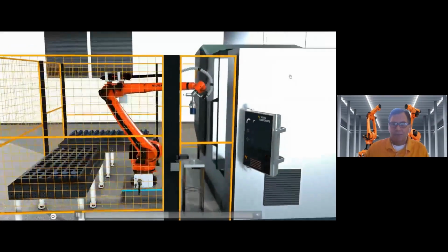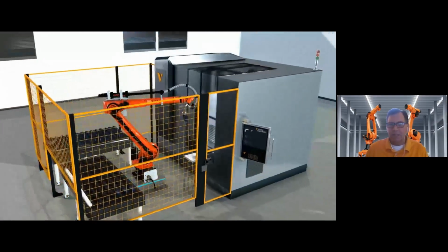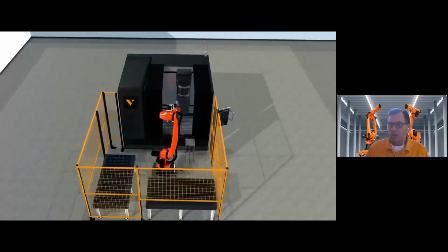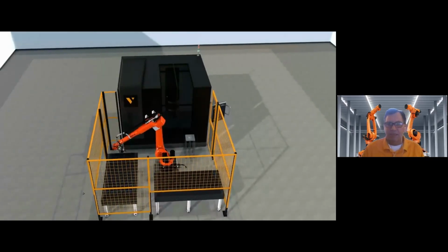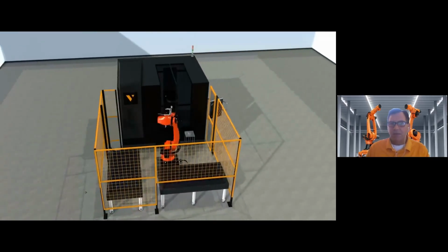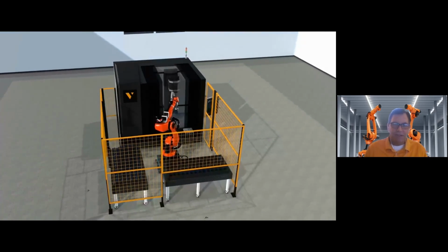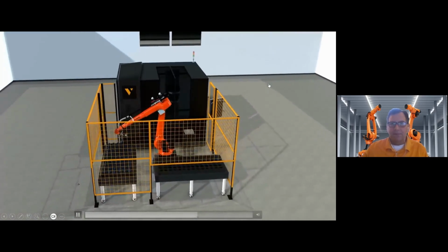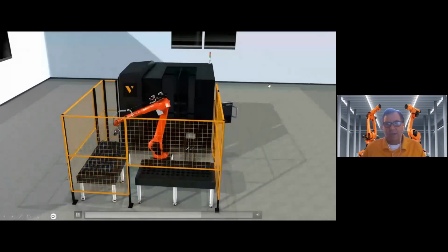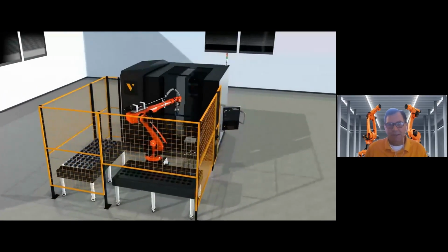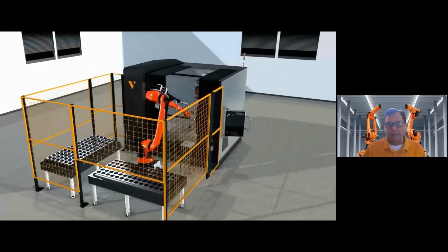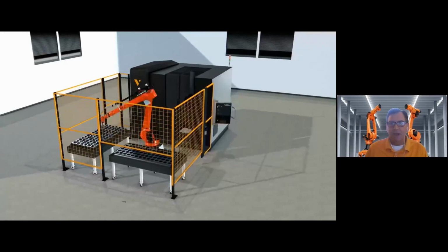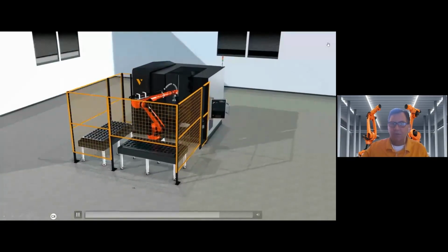Here's the same simulation, but a higher-end, more realistic simulation to show the whole process. So you can look at different views. You can see if there's going to be any potential bottlenecks within your facility, and any operator interfaces or ergonomic issues can all be checked offline. And if you're not validating, I'd say, 90% plus of the application offline, you're really wasting a good option or a tool that's available to you. It could save you a lot of headaches, could save you cost, and also improve your schedule.